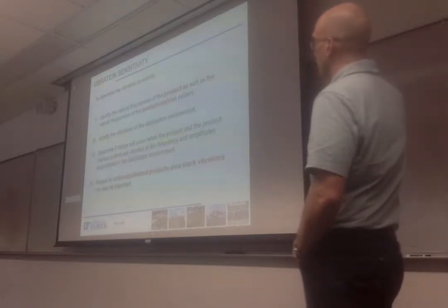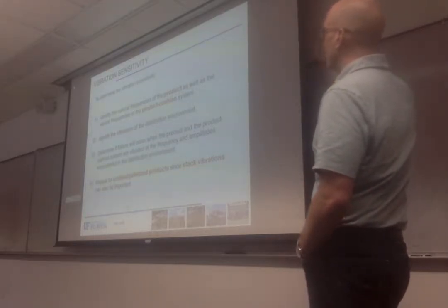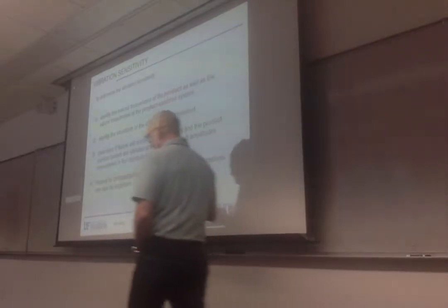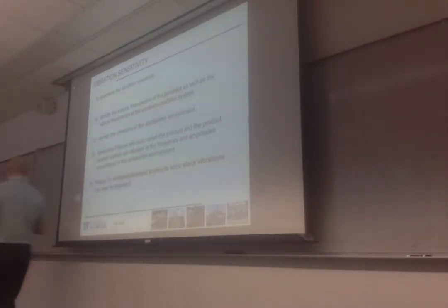So the first step here, you should identify the natural frequency of the product as well as the natural frequency of the product cushion system. How would you do that? Yeah, the sine sweep, remember? Okay, so you typically will have to set your product on the vibration table, and you'll have to do it at different levels.